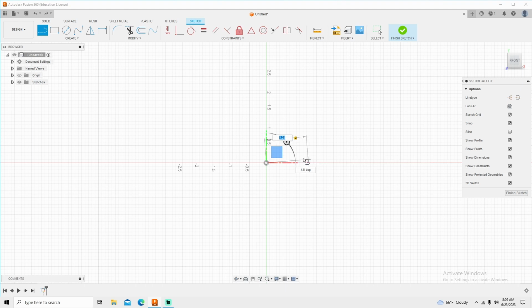Now you see there's two boxes here. There's one box that has 1.25 in it, and a box slightly to the right and down that's 0.0 degrees. If I hit tab, I can change that degree. Positive degrees goes counterclockwise. So let's say I want 180 degrees. Well, it just flips over to the left. Then when I click enter, I have a simple line and it holds my dimension for me. Now, if you don't want that dimension, you can click and you can delete that dimension.